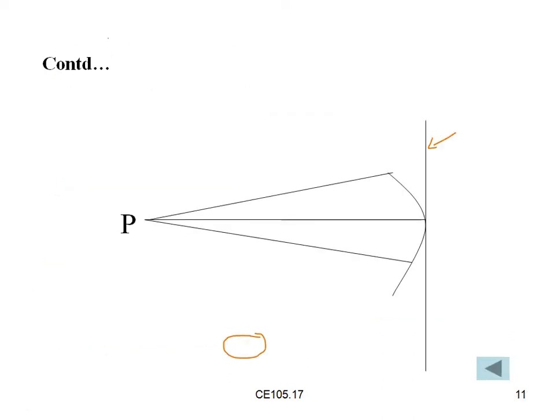Here the surveyor will be standing, this is the P point. He will be keeping the tape, catching here. This is the offset, and this is our chainage line. With the offset length we take the tape measurement and move it like this.